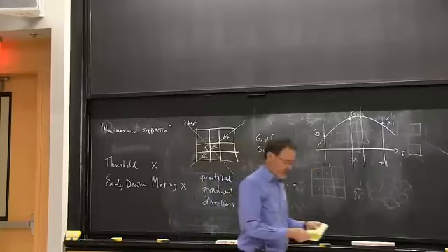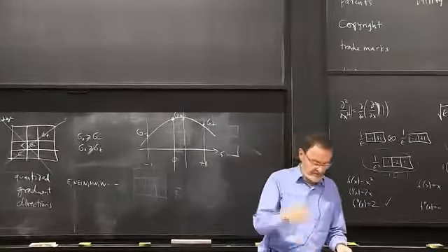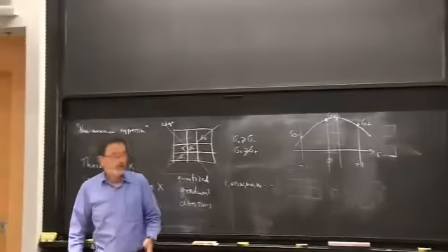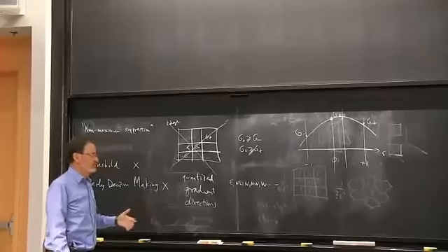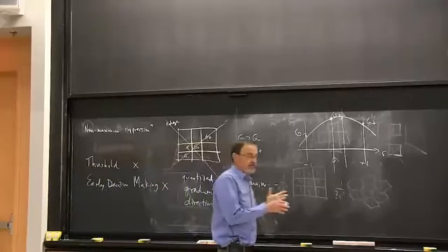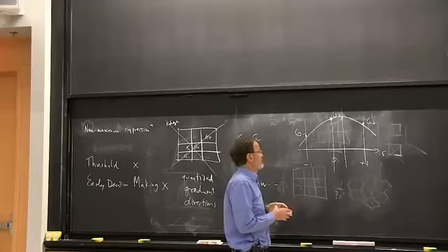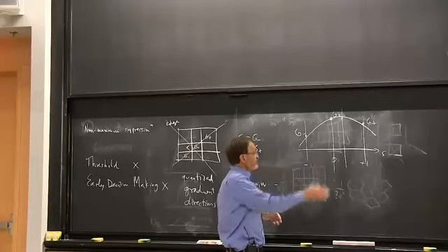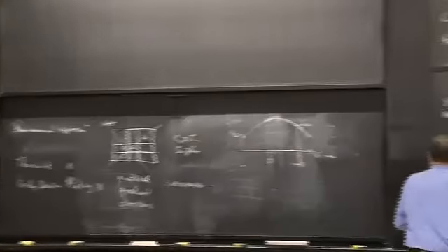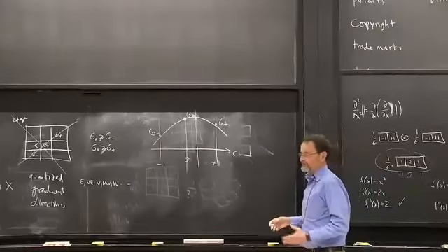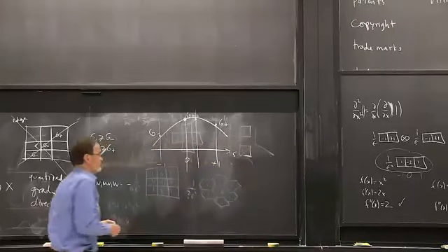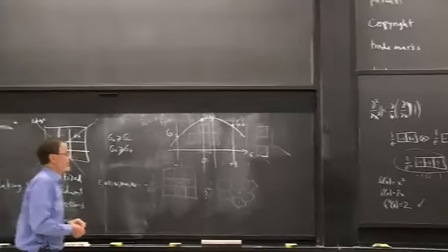So several points there. One of them is, why fit a parabola? Well, that's arbitrary. The shape of that curve depends on the optics, the image sensor, the thing you're looking at, but we only get 3 samples of it. So treating it as a smooth curve, the lowest order polynomial that will work is second order. So one option we have is to use that. And not to say that that's the only option or the best one, but it's a pretty good guess.